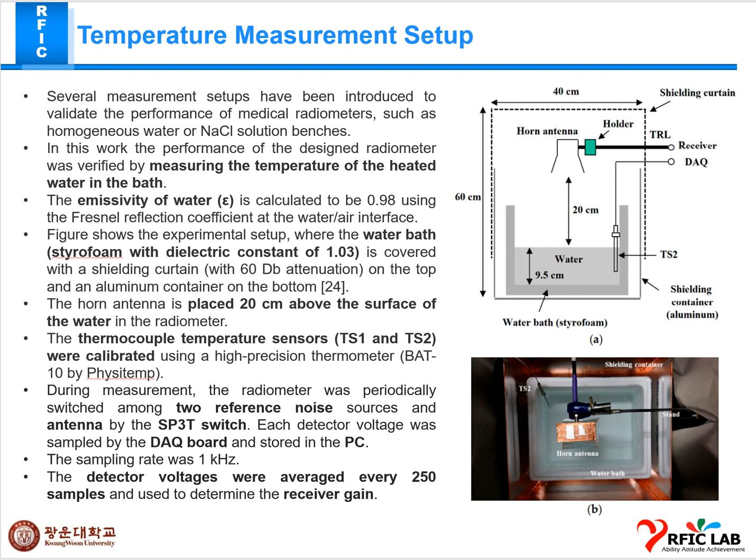In this measurement setup, it has a water bath, and the figure shows the water bath uses styrofoam with dielectric constant 1.03, covered with a curtain with 60 dB attenuation on the top and an aluminium container on the bottom, and a horn antenna is placed just above the water surface, about 20 centimeters above the surface of the water.